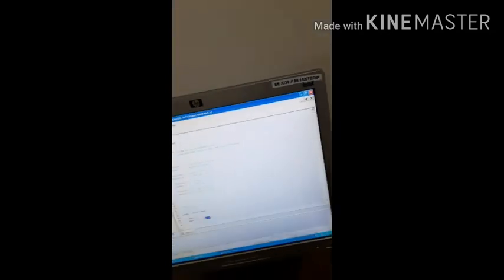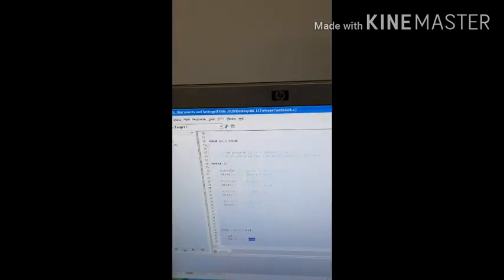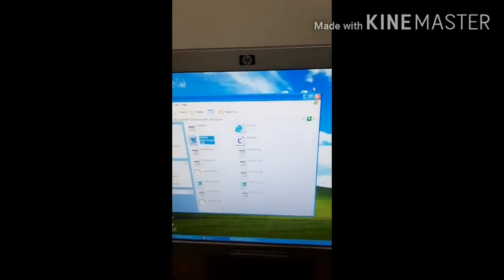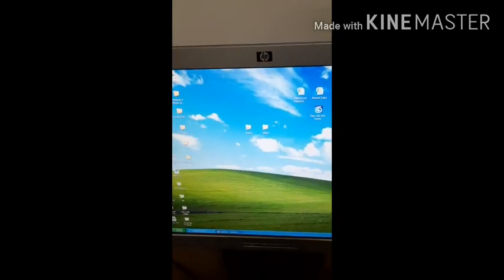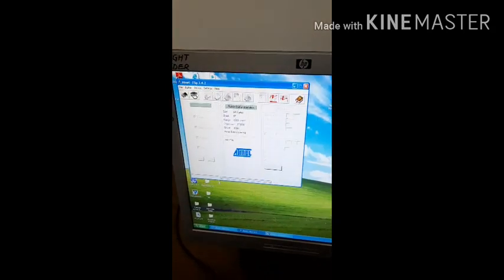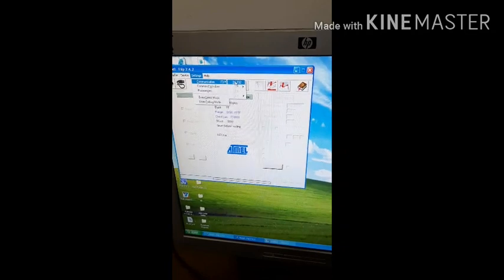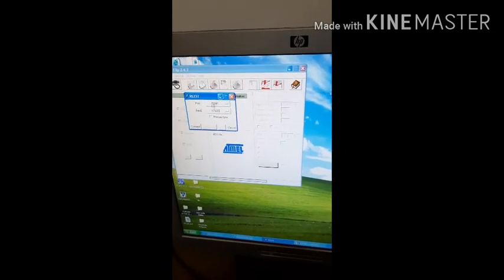So now we will try to see how exactly we will be able to control the stepper motor by writing the program. This program has already been written and its hex file is created. Now as usual, I will have to go to FLIP. As you can see here, this is the FLIP software. So settings, then communication, RS-232 with the default setting.